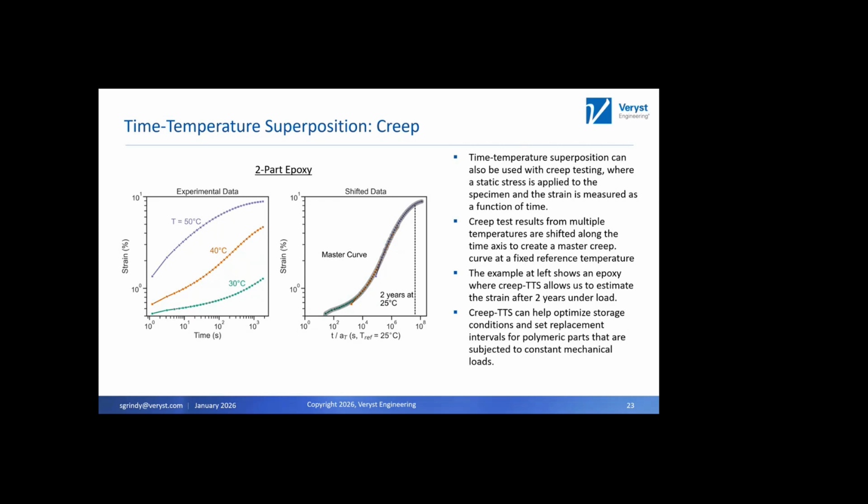an assumption, it is not something that is easy to justify without actually fully doing the 2 years of testing, right? Is that this material is, fancy word, thermorheologically simple, meaning that we can use this time temperature equivalence as a good mental model for the material's deformation behavior. The more physical description of that is that the creep deformation of the material is controlled by a set of mechanisms that have uniform temperature dependence.